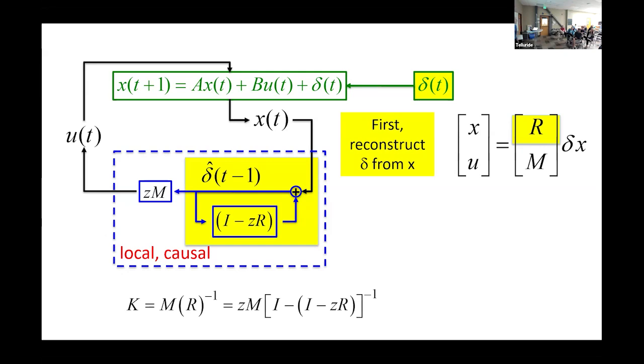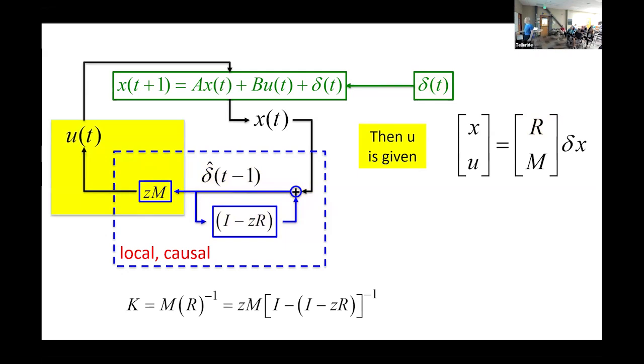And so I think this is what's implemented in the brain. I want to show you why. Because this can have delays, everything in it, because we put the delays in M and R, and then they reflect themselves in the inside thing. So notice this internal model is the internal model of the closed loop system, not the open loop. So once you do this, this is given.